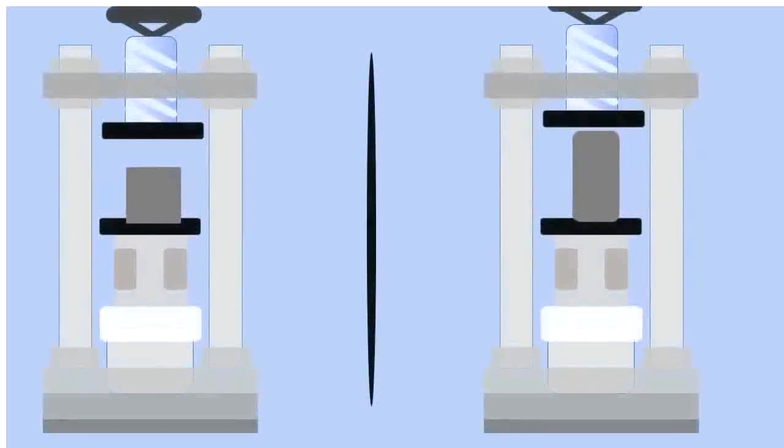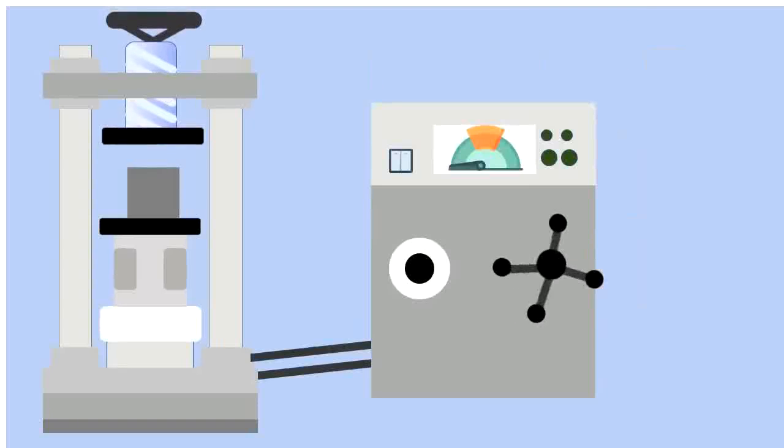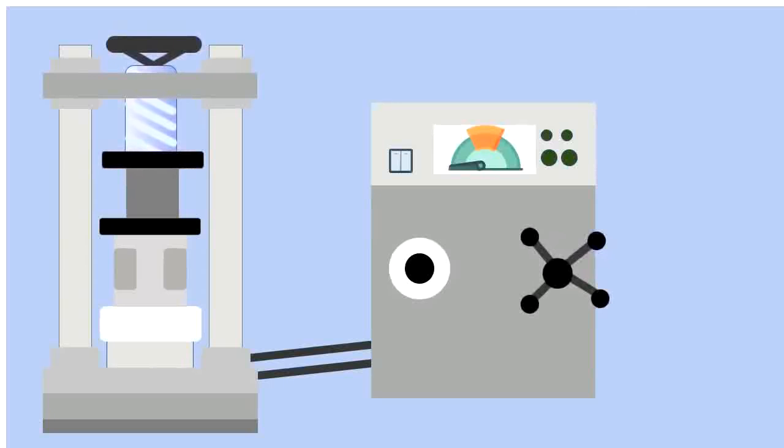Then, the specimen is placed on the compression testing machine. The cube specimen is just placed on the bearing plate, while the cylindrical specimen is placed vertically. The instrument is then adjusted such that the specimen is correctly placed on the equipment.